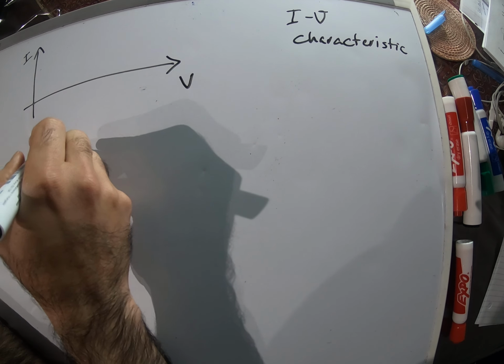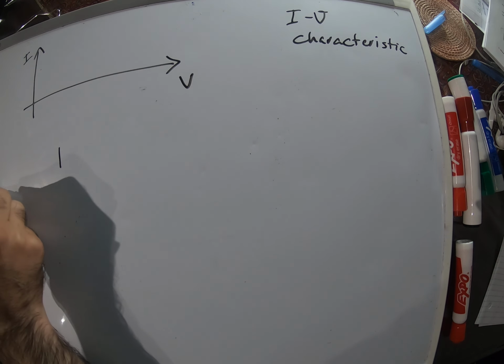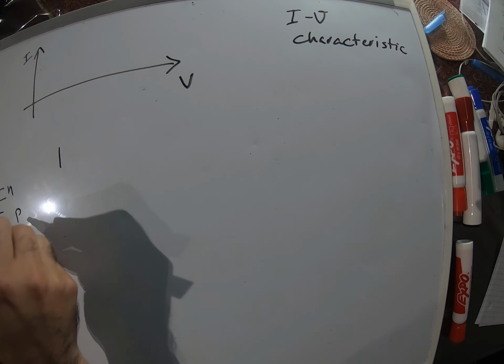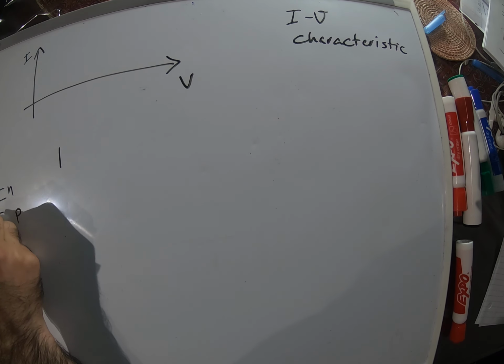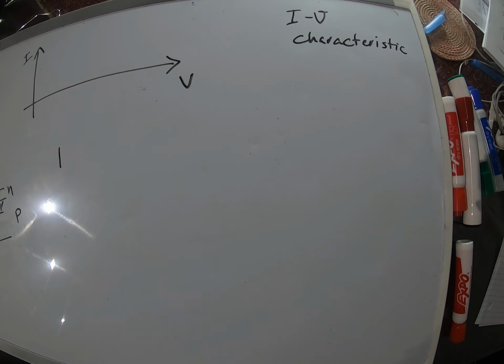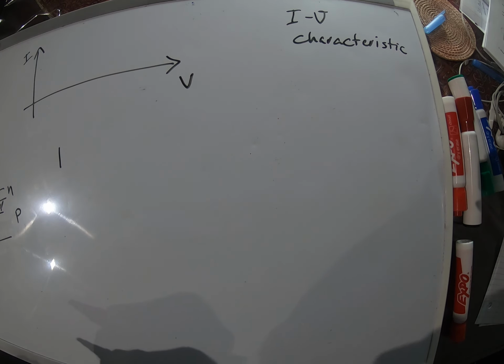So as you saw previously, a solar cell has a P and an N junction, and it has a depletion region here. And if I want to be more accurate, the N region is a little bit thinner to make the depletion region a little bit wider, and also make the solar radiation go through the depletion region faster or more efficiently.